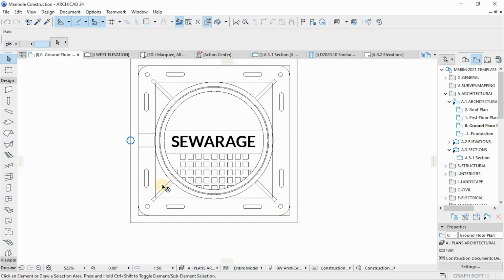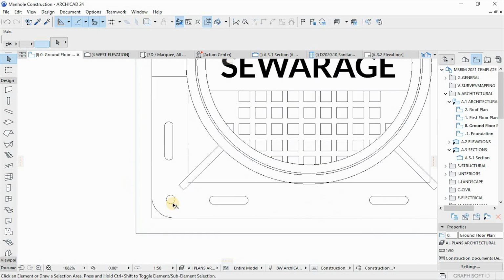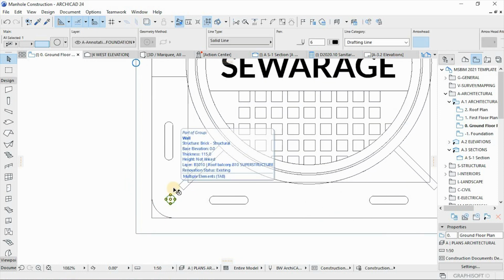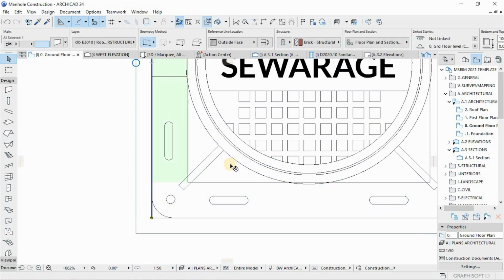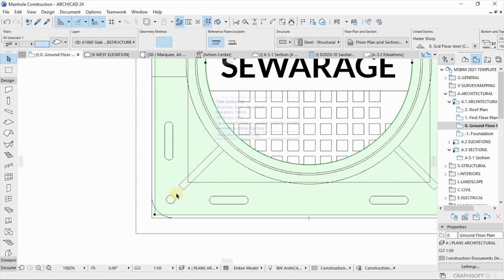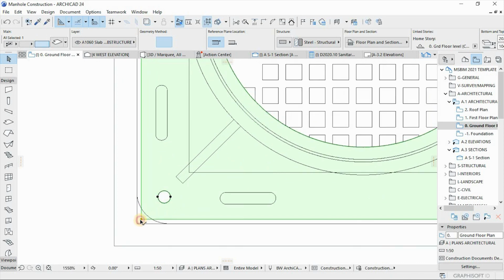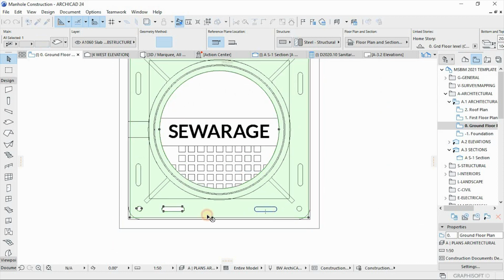Remember, these holes are the ones we're going to use to anchor it to that plate. I already have this as lines. What I'm going to do is pick the top lead, this one, then use the magic wand to create these holes, like so.